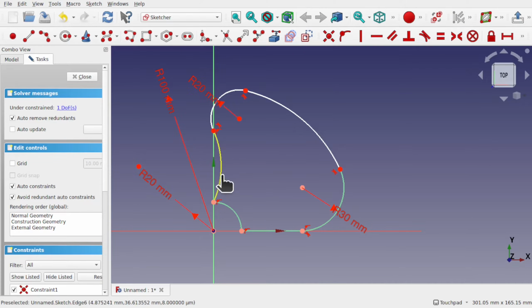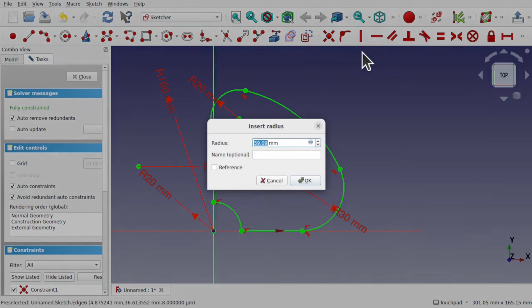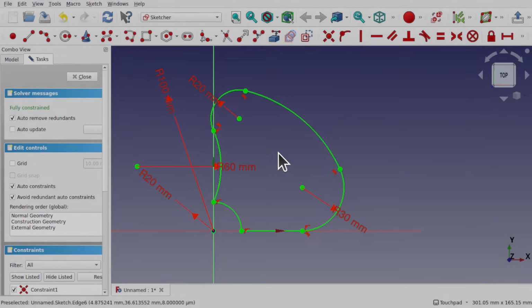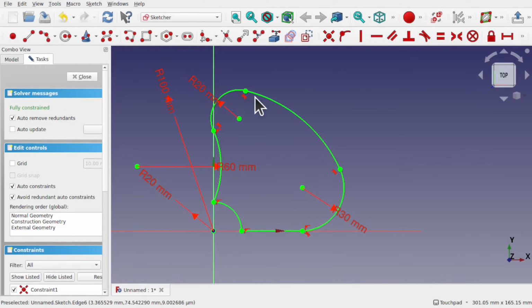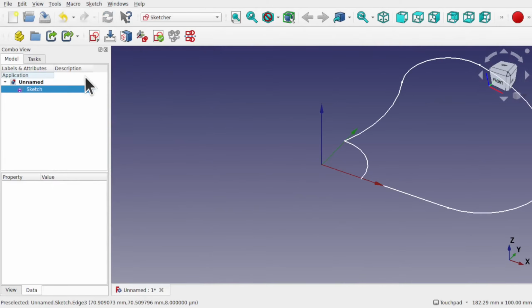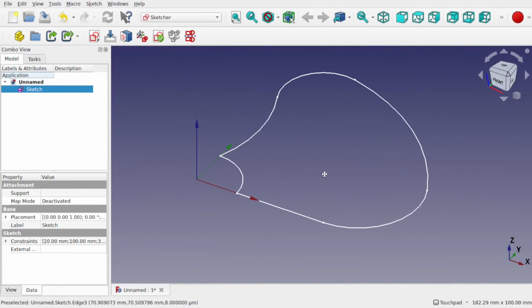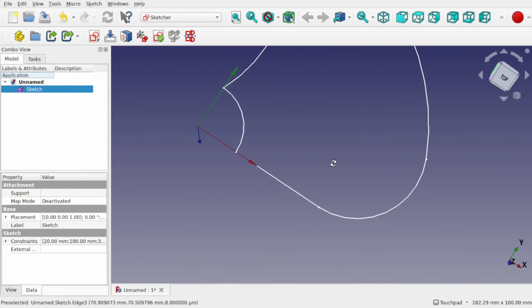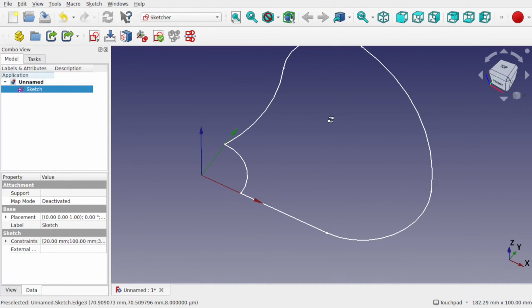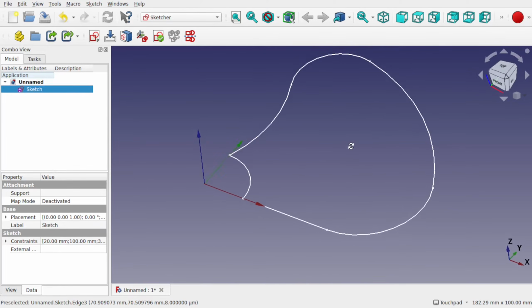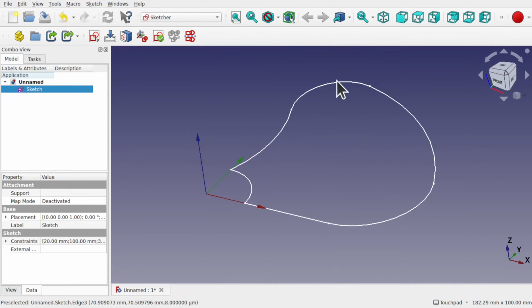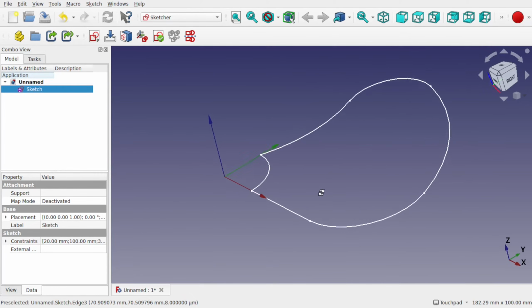Finally, let's take this arc and add a radius of about 60 millimeters. So we've got our fan blade. Let's hit close. So that's the start of our fan blade, and we can see how that sits in the middle. So at the moment we've got a fan blade, but we need to have this angled and arrayed around a center point. Let's deal with the angle.